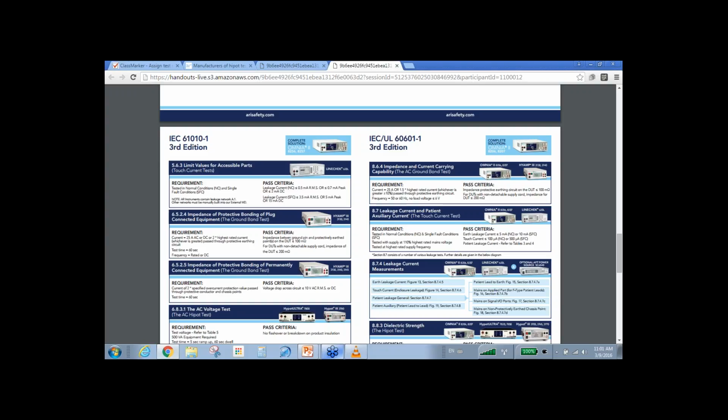It's also called a hot high-pot testing, and at this point, your DUT or device under test is actually powered up and running normally, and then we're applying a high voltage through an isolation transformer and measuring the resulting leakage current.